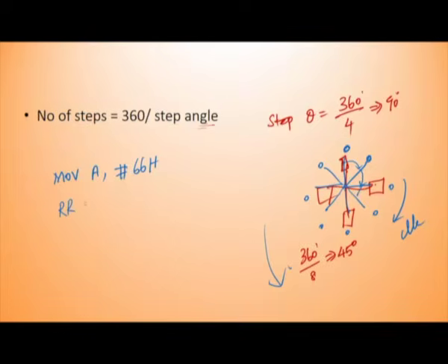So the given data value is rotated. Initially, considering only a single nibble, the value is 0110. After rotating it becomes 0011. Considering A, B, C, D, the corresponding coils will be energized. The same process you can repeat a number of times.